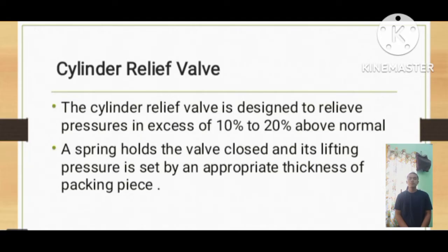Its main purpose is to lift when overpressure occurs in the combustion area. The resultant combustion gas is spilled through a flame-proof pipe to the deck. Causes of lifting: first, incorrect fuel pump timing, and second, air start valve stuck open or wrongly timed.